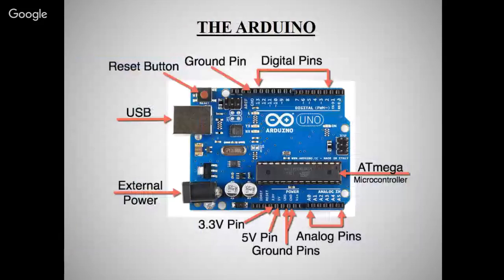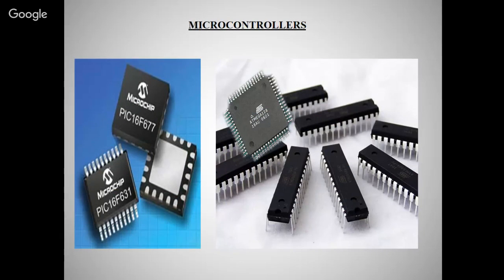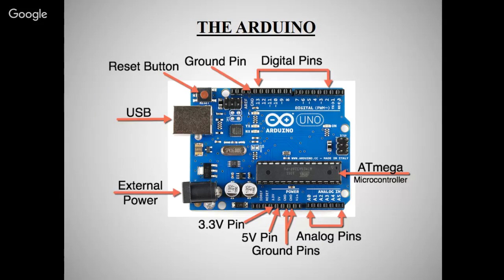In a simple way we can say that it is the brain of the system. When you get the light values from the LDRs, the controller will say where the maximum light is. There are four LDRs, and it compares the voltages from one LDR to the others. Then it will give the output to the motors. So it is the brain of the system. Here I used the Arduino microcontroller.